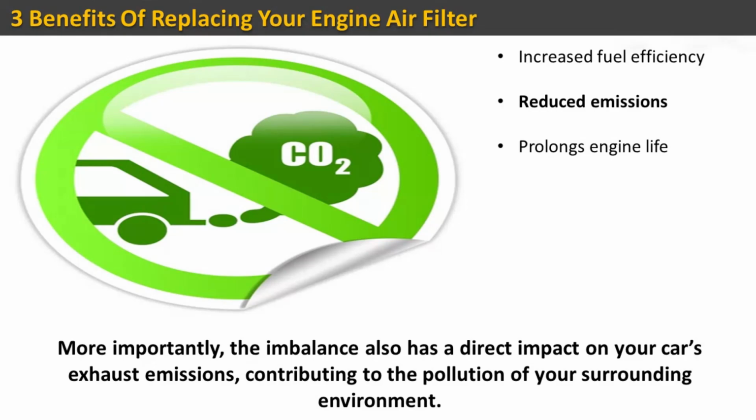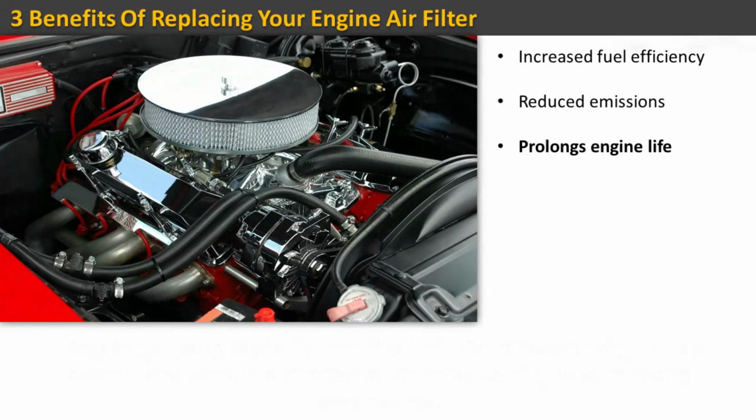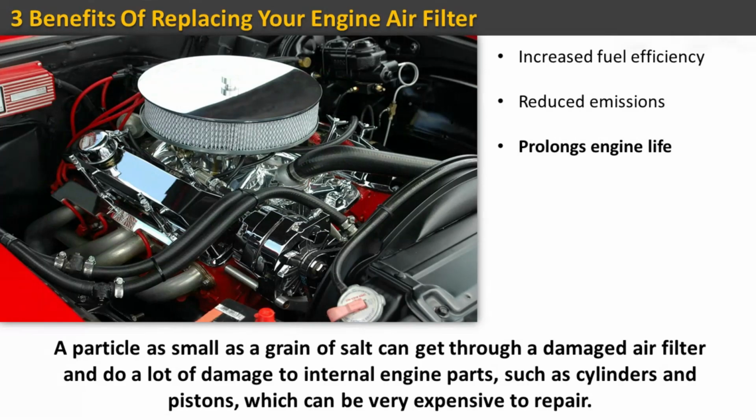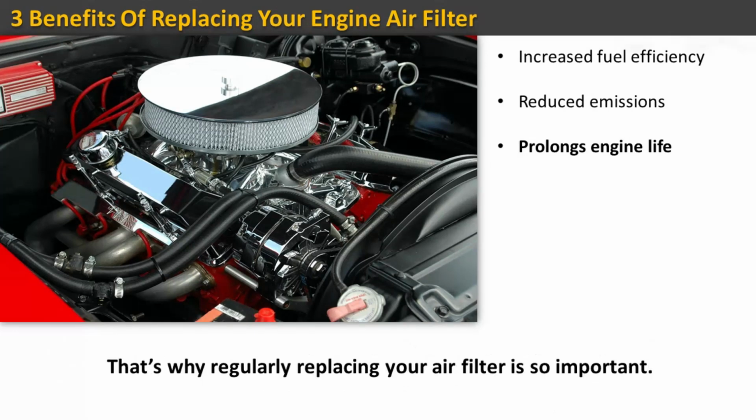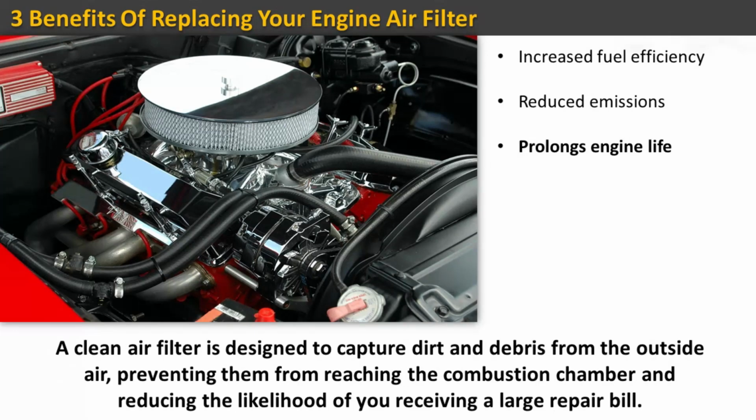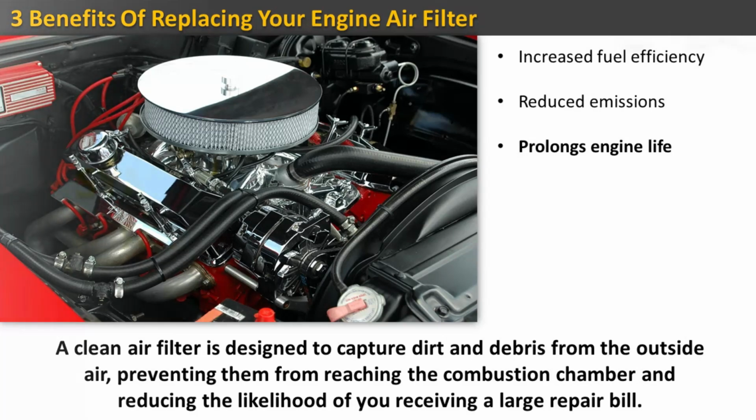Prolongs engine life. A particle as small as a grain of salt can get through a damaged air filter and do a lot of damage to internal engine parts, such as cylinders and pistons, which can be very expensive to repair. That's why regularly replacing your air filter is so important. A clean air filter is designed to capture dirt and debris from the outside air, preventing them from reaching the combustion chamber and reducing the likelihood of you receiving a large repair bill.